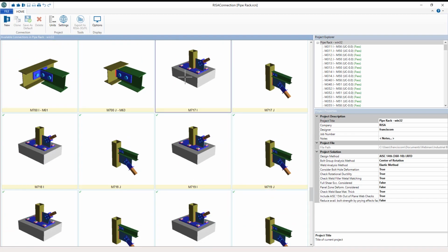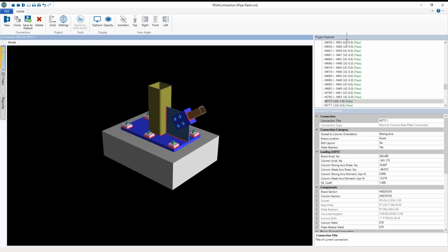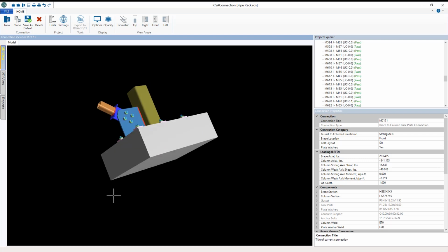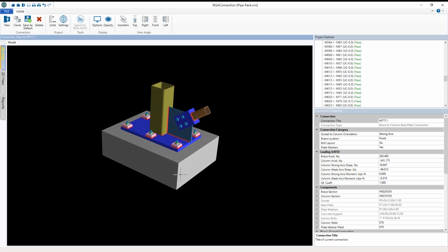So as you can see here, it's telling you the governing unity check and for the correct load combination. I've already detached the model, so the load combination isn't registered just yet, but that's a feature that's available to you once you have the program integrated with RISA-3D. So at this point, you can really just pan around the model. This is a great way to do it in 3D. And you can also click on this, so it's also interactive.